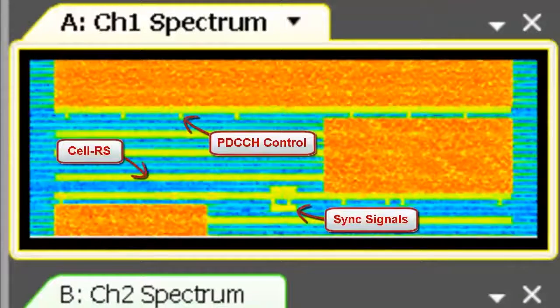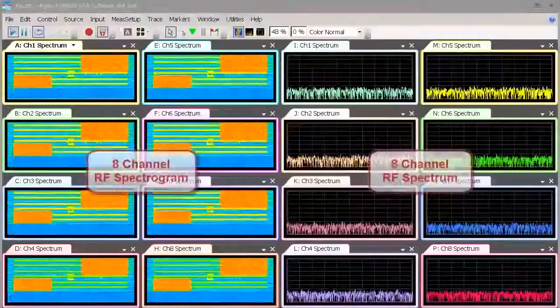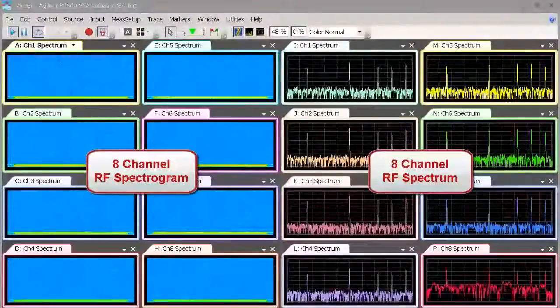Note this feature does not require any demodulation at this point and is a very useful debugging tool when investigating unexpected RF or scheduling issues, especially when those issues impair normal demodulation of the signal.